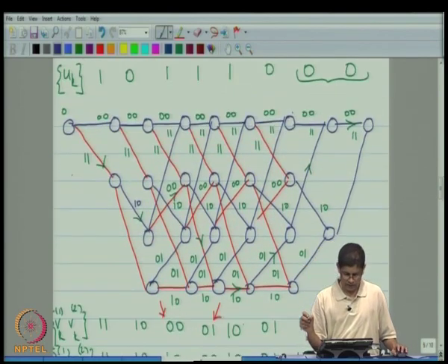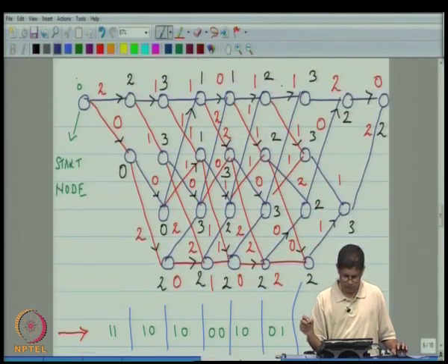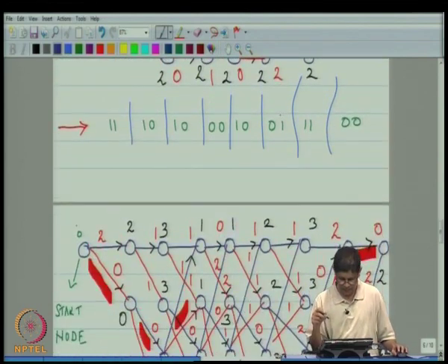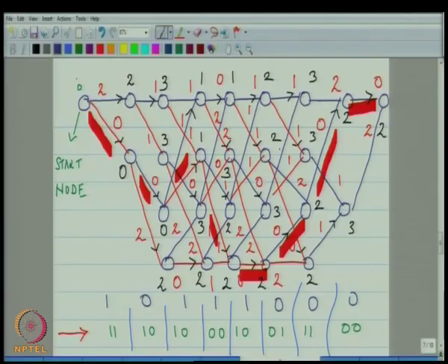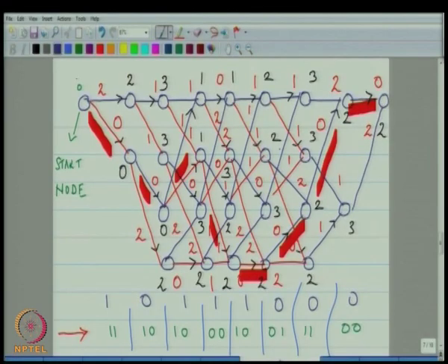and that is not surprising if you know a little bit more about the properties of the code. Anytime you create 2 errors, you are always going to be able to decode. In actual fact, you can decode a larger number of errors, but then you have to worry about where you place the errors. Okay. So, that is how Viterbi decoding proceeds.